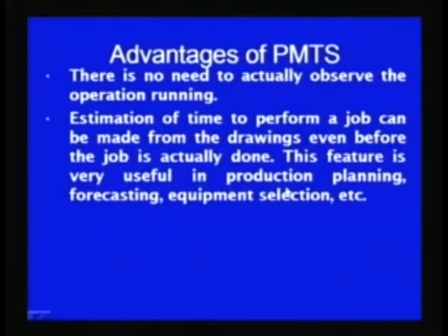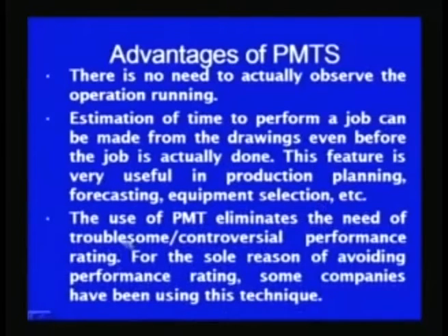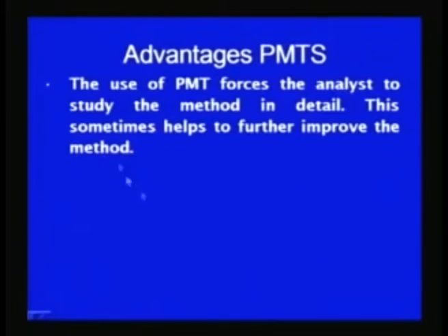This feature is very useful in production planning, forecasting, the equipment requirement and selection of the manpower. The use of PMTS eliminates the need of troublesome, controversial performance rating of the worker by the time study man. For the sole reason of avoiding the performance rating, some companies have been using this technique extensively.